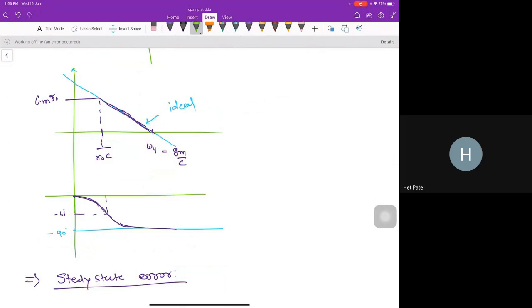Previously I had a pole at the origin, now I have the pole at a certain frequency, right? So that is what I am getting here: a finite DC gain due to this R0. And why that R0 comes, please keep in mind that you will see the circuit and you will get that, oh, this is R0. In a practical circuit we will have some specific resistance.